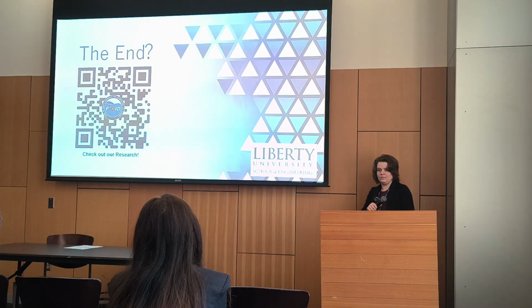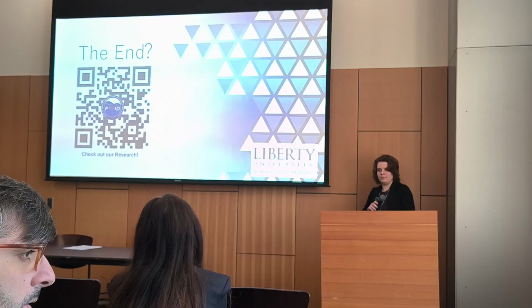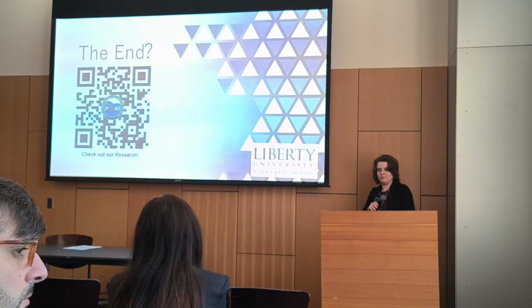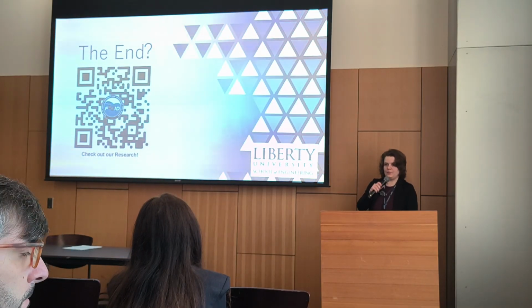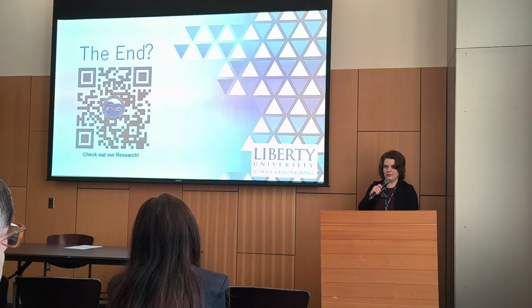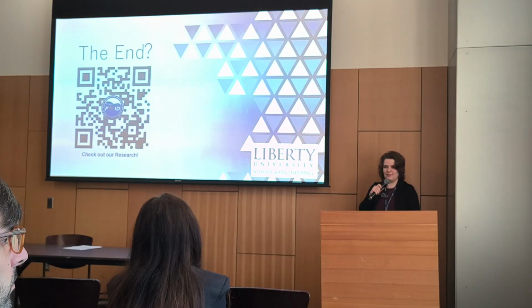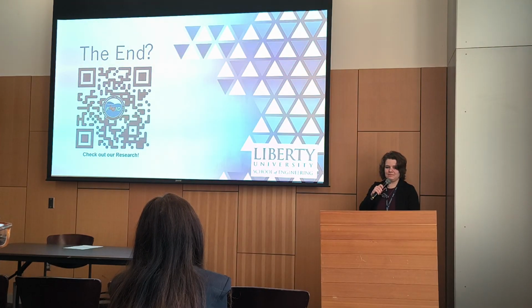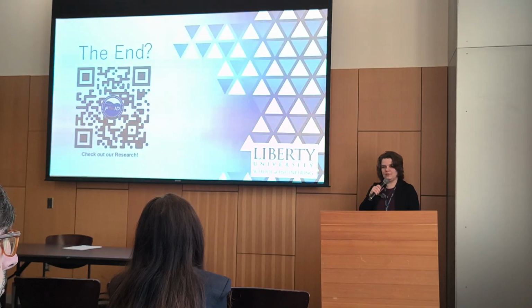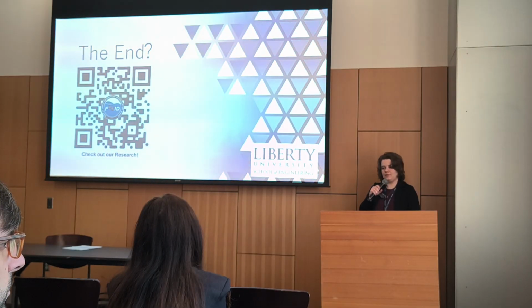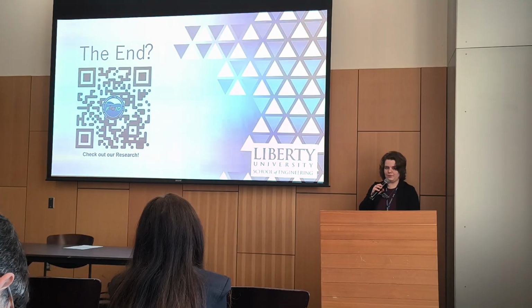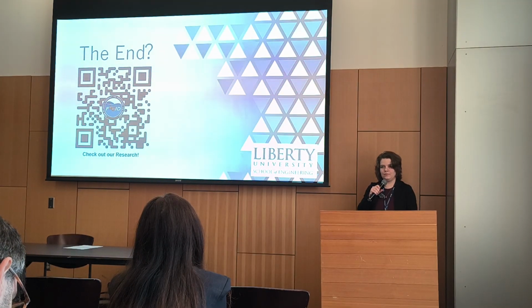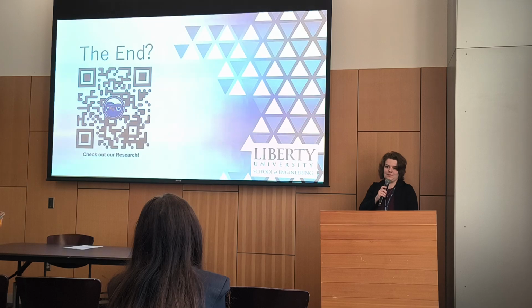So how long did it take to run your simulations? Was there a relative difference depending on the model you selected? SST was the one that we were pursuing first because we knew it would be the least amount of time, and that one took like a day and a half, I would say, with all of our beginning stuff. And then SST and LES with just this coarse grid was taking like 2 to 3 days. We ran those at the same time.